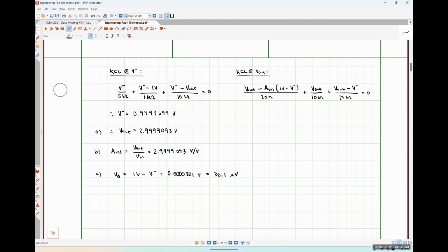Zero current flowing into your... So, yep, no current would flow into or out of our input terminals. So we can see that even though we've used the practical op amp model, that is pretty close to happening here, right?